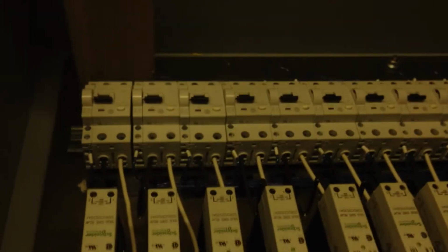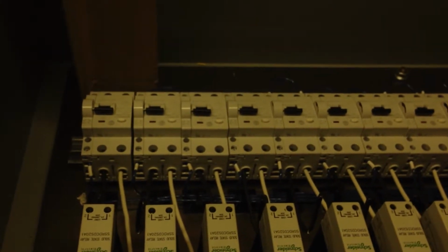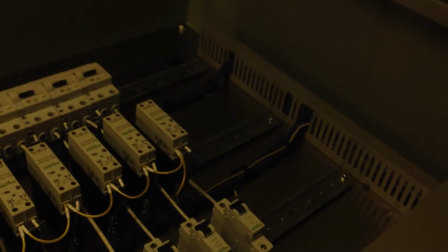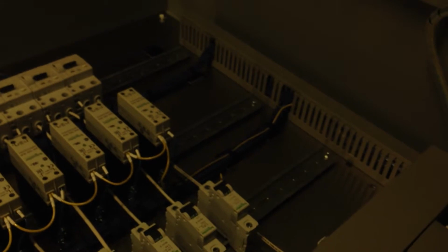All you really have to do is put your power in at the top. Down at the bottom, you hook up your heat trace directly to those GFI breakers. And then over here, you hook up your RTDs, labeled 1 to 12. We left a little room over here on the left, just so you can add another 4 stations if you want to. And I left room right there for another card, so we can add that as well.